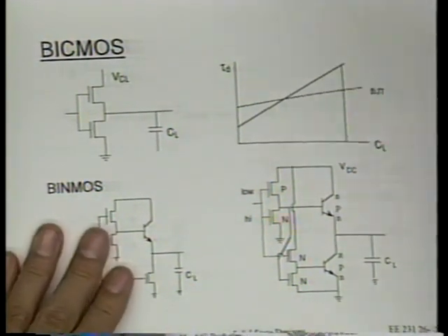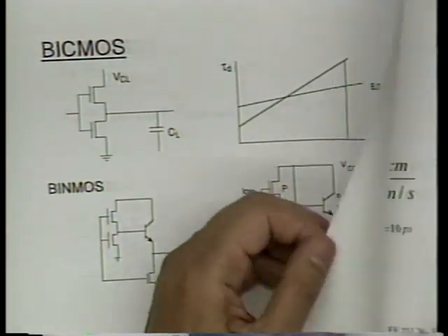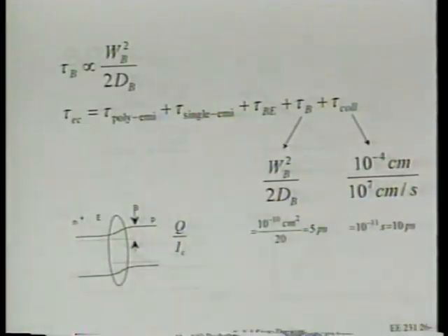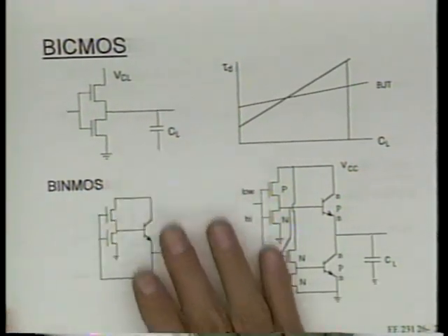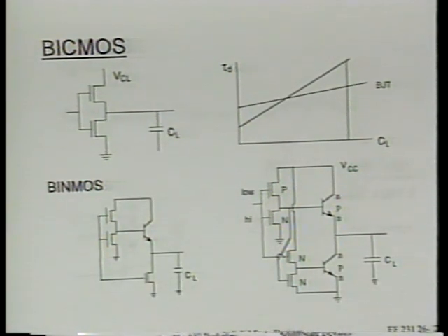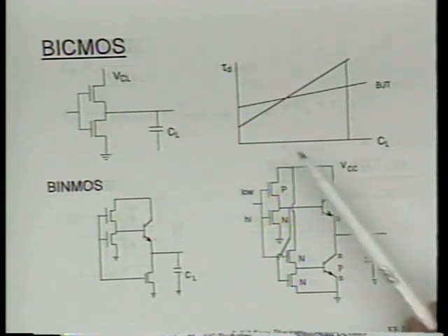Today, when we say BiCMOS, we typically mean using the bipolar transistor for RF, let's say, and using CMOS for everything else. But if you have the bipolar transistor, you can also use it as the buffer device in some portion of a logic circuit where you need to drive a long line of interconnect, for example. You don't have to use a very large W CMOS transistor to drive it. You can use a bipolar transistor to drive it, right? Because it's a large I, okay? And you can do that, and that circuit will look like this.